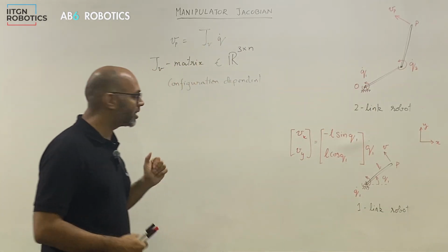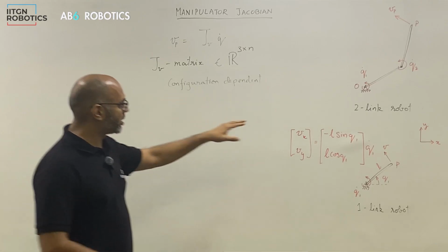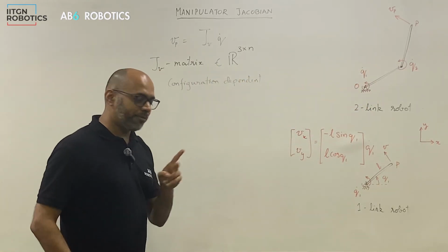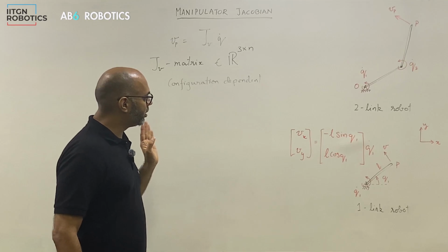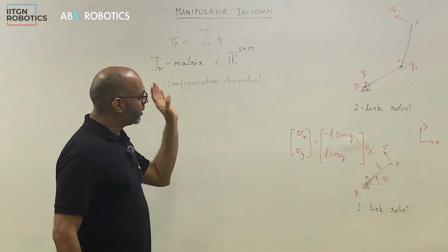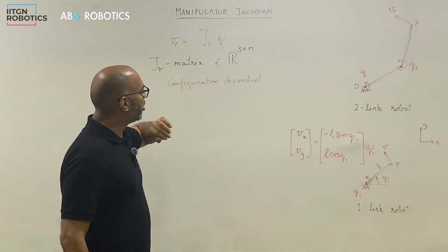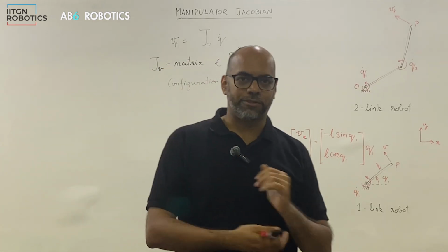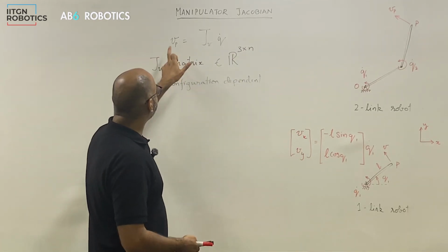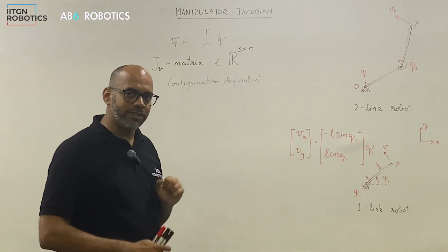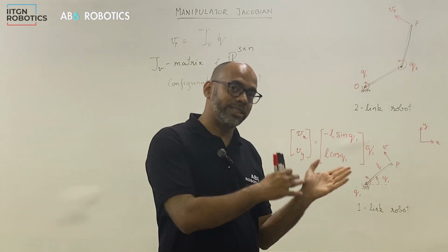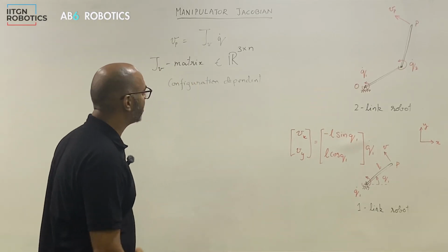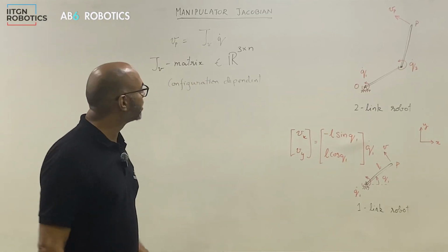relationship between the velocities, because first it helps you relate what's happening at joints and end effector. Second, once you start thinking about the dynamics of the robot, you want to compute things like the kinetic energy, for instance, then you need velocity, and for that again you would use Jacobian. So in dynamics, you would see Jacobian plays a role once you start deriving equations of motion. In the derivations, you would often use Jacobian.